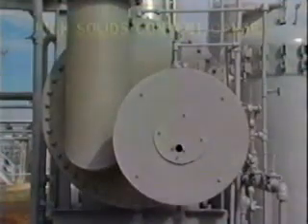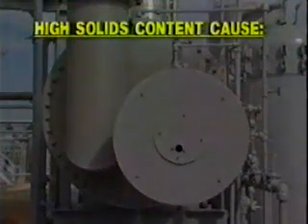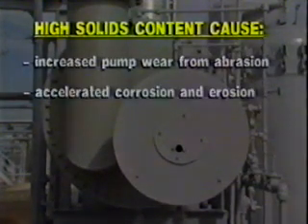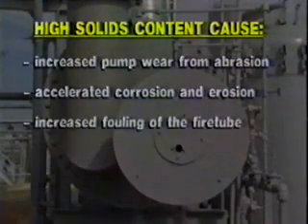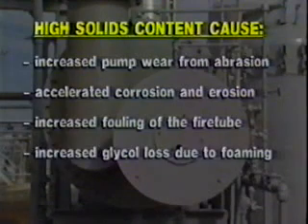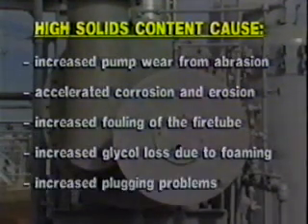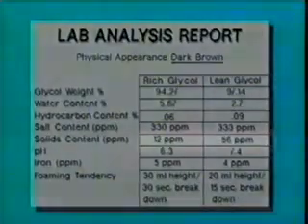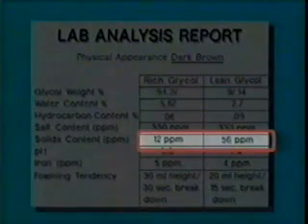High solids content in glycol causes the following problems: increased pump wear from abrasion, accelerated corrosion and erosion, increased fouling of the fire tube, increased glycol loss due to foaming, and increased plugging problems. The solids content of our sample seems to be in the acceptable range.